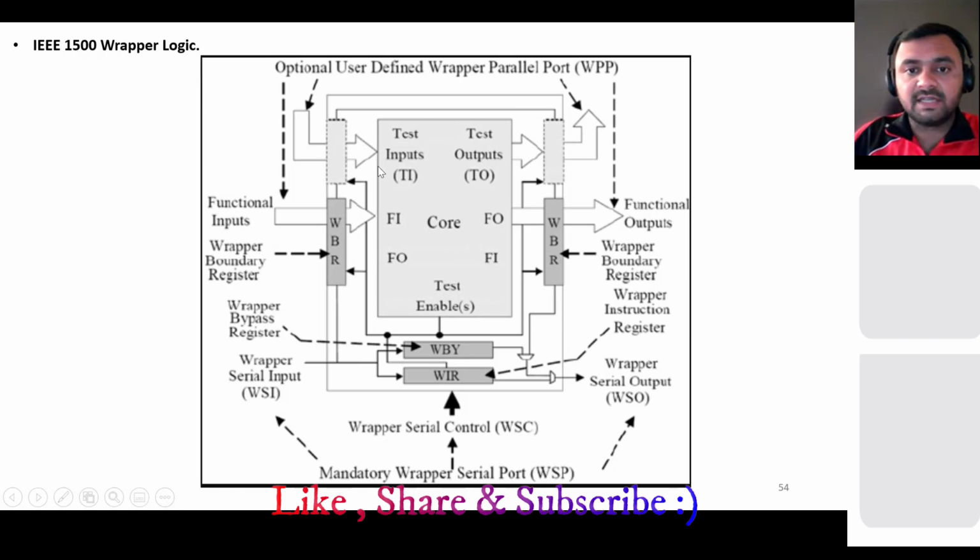So basically, to isolate, suppose you have 10 different cores, you have a top chip and 10 different sub blocks in that chip. We test those using this wrapper logic. Suppose you want to skip the first 2 cores and test the 3rd core. You can use this bypass logic to bypass those cores and test only the 3rd core. The mechanism is the same as for the top level logic, but there is a little bit of logic difference here. So you have a TDI, test data input. You have a wrapper serial input here.